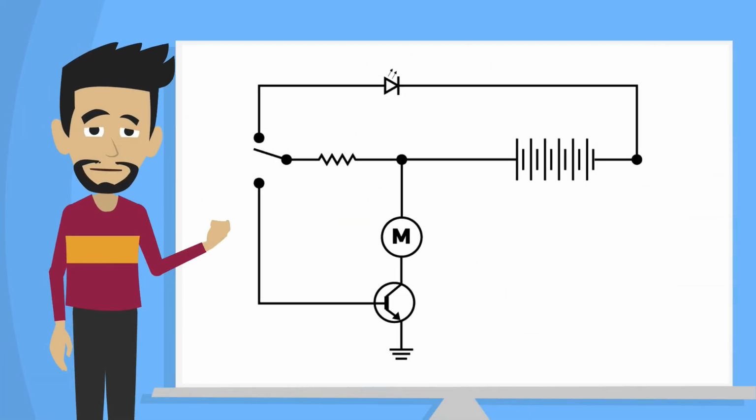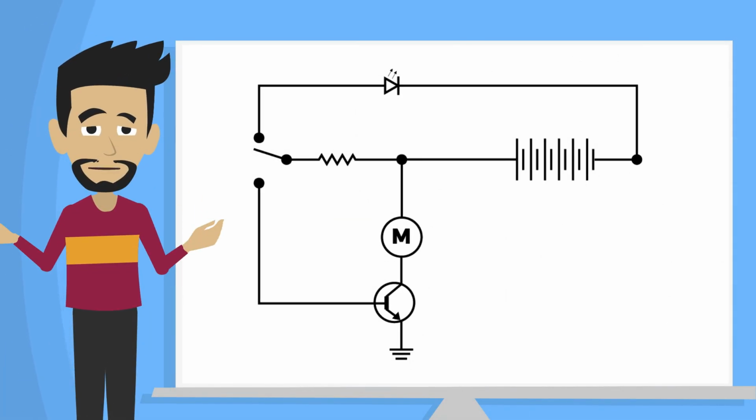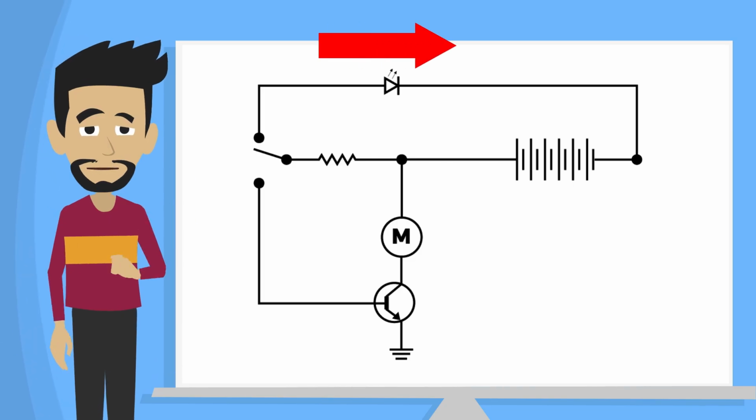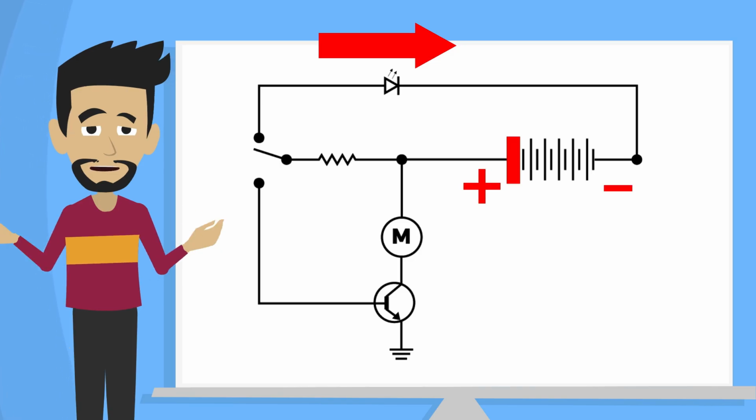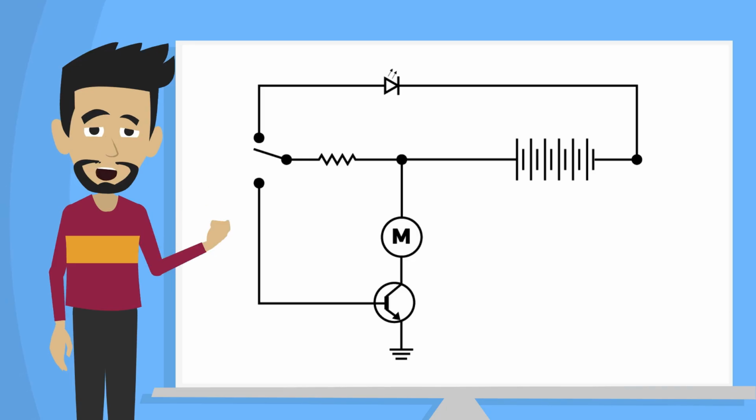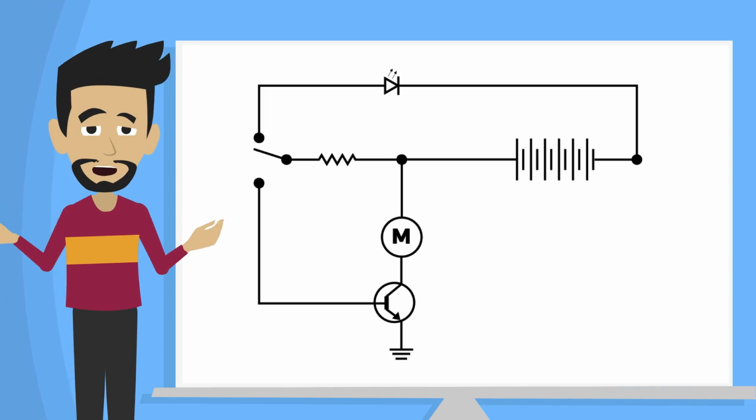In circuit diagrams, polarity is shown by the electrical symbols. For example, an LED symbol has an arrow showing you the direction the current can flow. A battery always has a plus and minus side indicated by the long and short signs in its symbol. Following these norms helps everyone to understand the correct way to build the circuit.